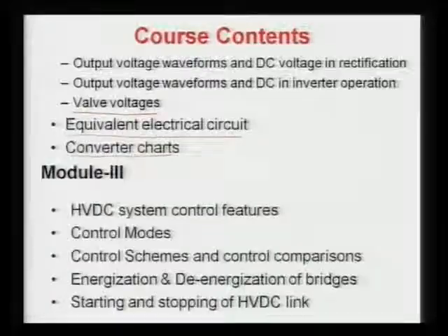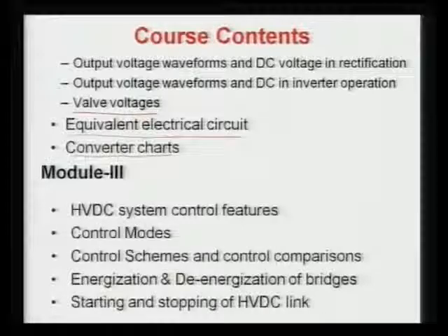One is the DC voltage and DC current, where we will see the impact of the DC variables and the current converter chart will be drawn. Another one will see the AC variables, with P and Q as your axes, and then we will see the power factor, apparent power, AC current, and reactive power as well, in another chart. So these two varieties of charts will be discussed, and then we will see how, based on that, we can analyze for any particular current and get the voltage U and other angles as well.